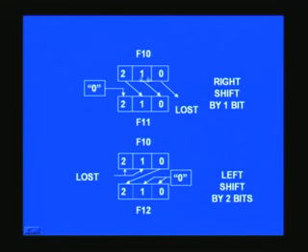And once you right shift this one, what you are going to do is just shift it here, then this 0 bit position, whatever data is in that position, it will get lost because we are not storing it. And if you want to store that, you can use some other Verilog statement to store in case the need arises, otherwise you do not really bother about that. So, similarly 2 and 1 will occupy 1 and 0 of the target.